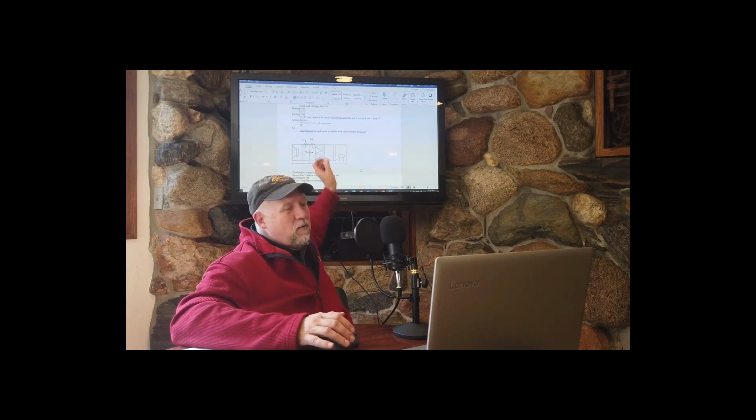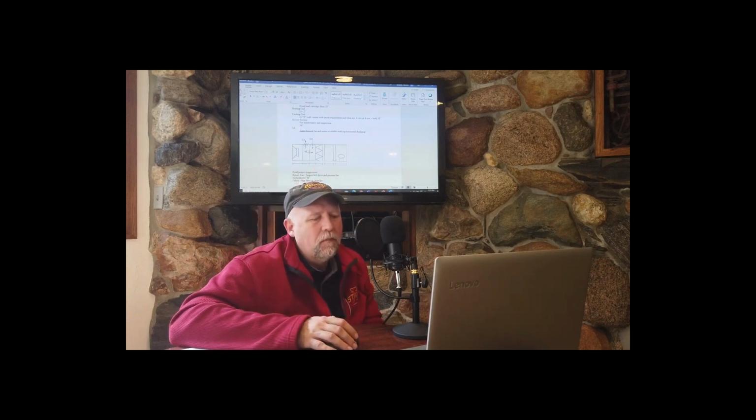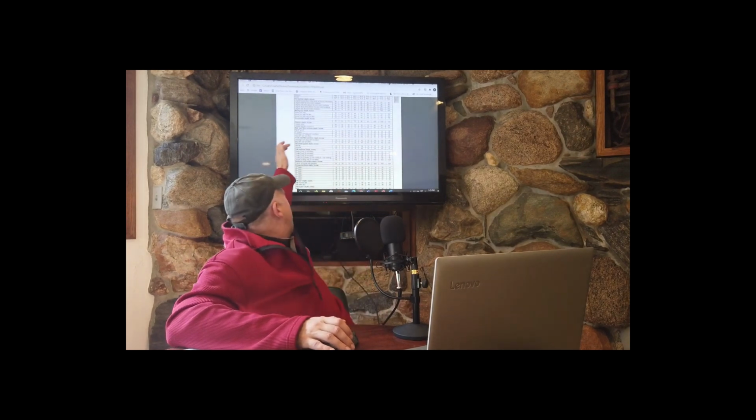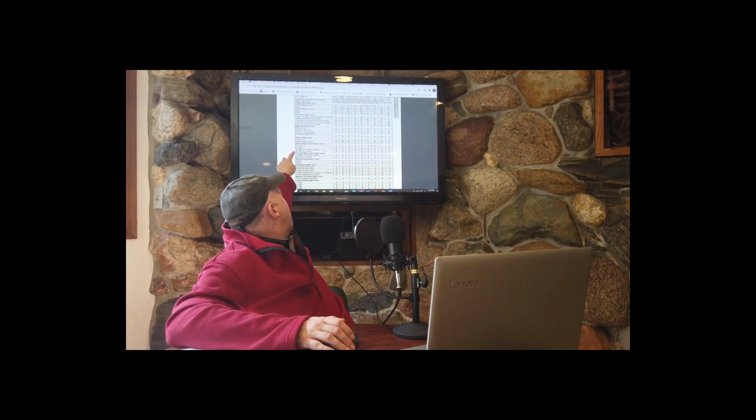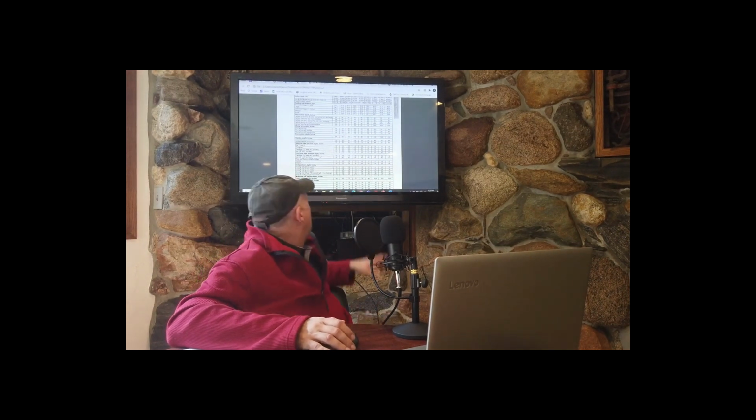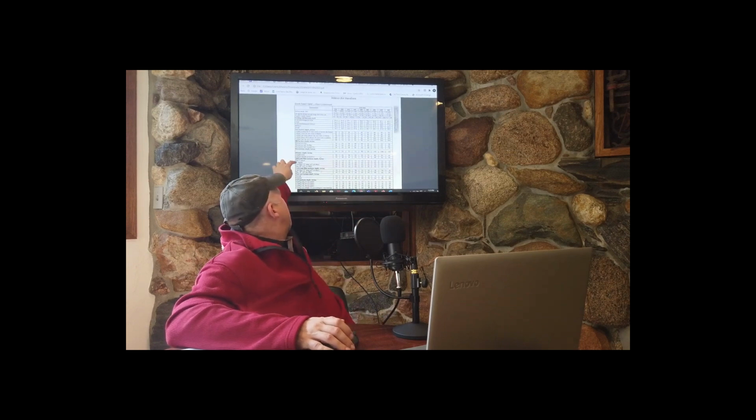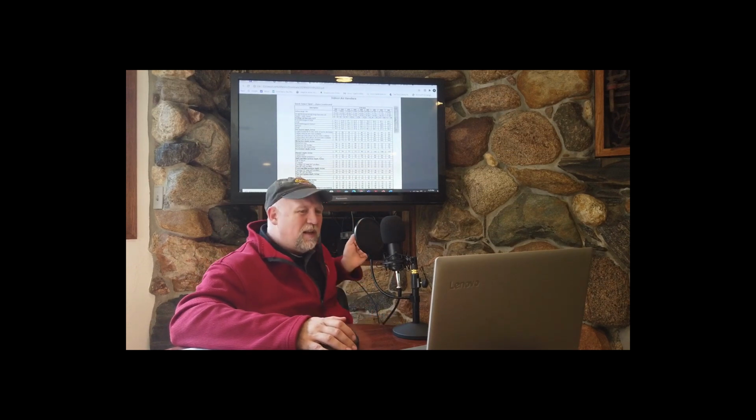All right. After that, we have the filter section. Well, which filter section should we use for this? And that's where we list a whole bunch of different choices. We've got flat filters, angled filters, cartridge filters, bag filters, right? Now, the first ones of these are side load. Side load is where you slide it in from the side of the unit. But for something as big as this, that's a long way to push filters through. We probably want a front load filter.